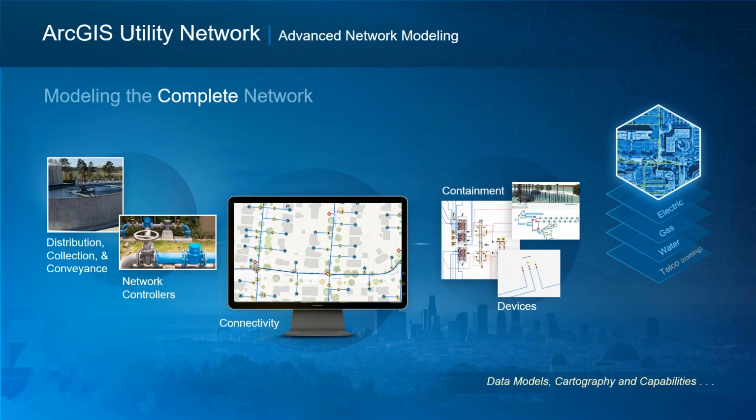The utility network also provides the ability to have much better connectivity with a whole set of connectivity rules that can be applied to the utility network to define how features actually interact in the real world. Previously, we would have to model that connectivity with coincident geometry. Now, through the utility network, we can actually utilize things called associations. So not every feature has to be geometrically coincident in order to actually be physically connected.